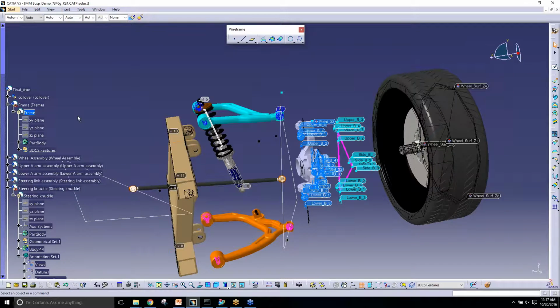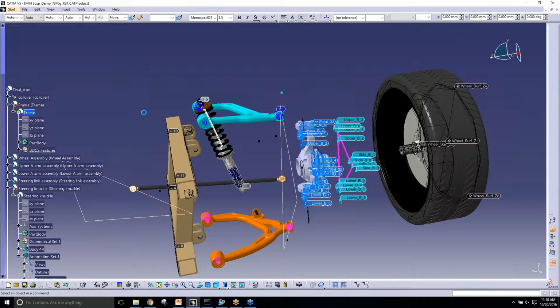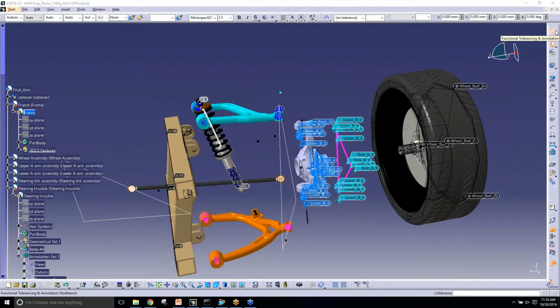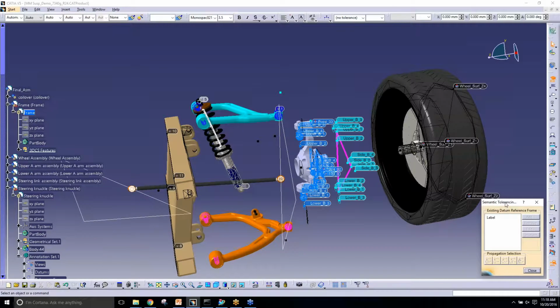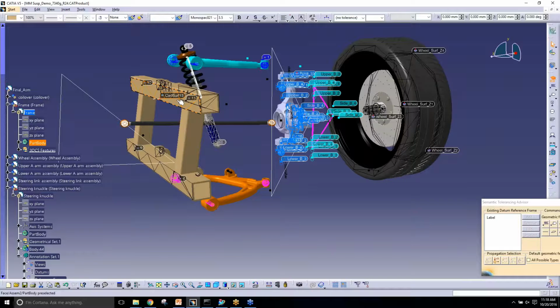So you're going to make GD&T in CATIA. Yep. And then you're going to pull that GD&T over into 3DCS. Correct. From CATIA. Yep. So now I'm going to switch over to my FT&A workbench, so function, tolerance, and annotation. And the dialog is called the tolerance advisor. So right now I have nothing in this frame. There's no 3D or FT&A. So I'm going to create just a plane, or I'm sorry, a datum right here on these two features.